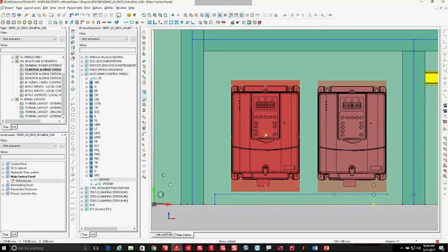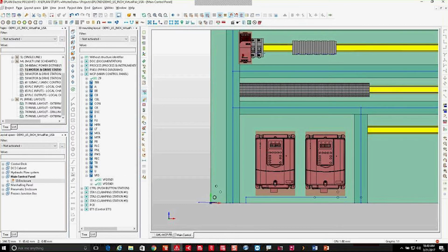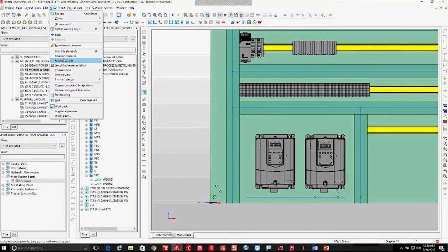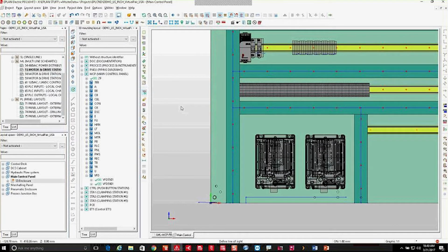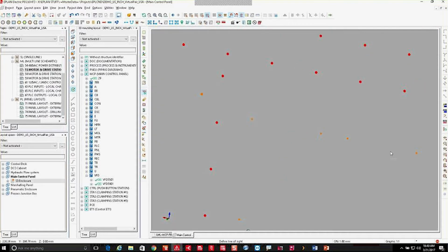So as I go ahead and place this component down, again, as I mentioned earlier, the component comes in with part information. This part information contains not only heat dissipation information, it again shows you the drilling data. So as I laid that component down, I got the drilling data for that component to be placed.